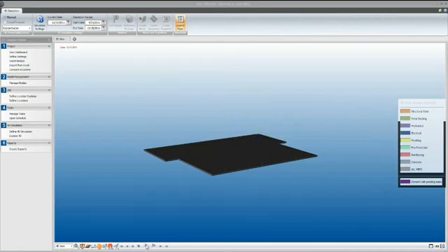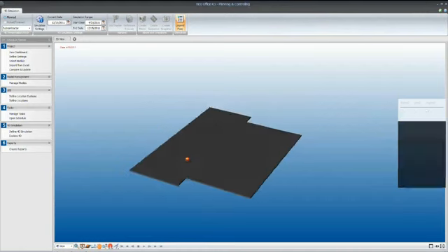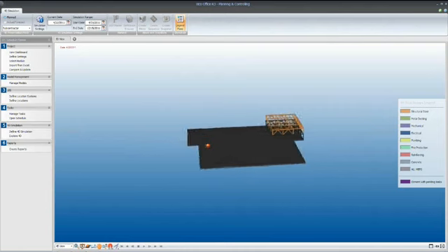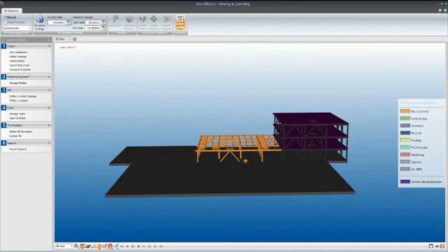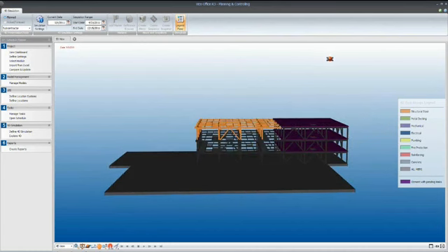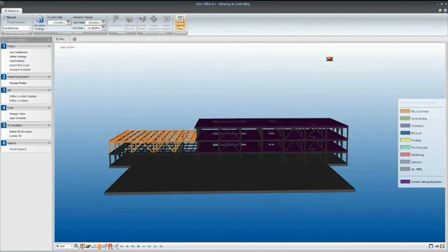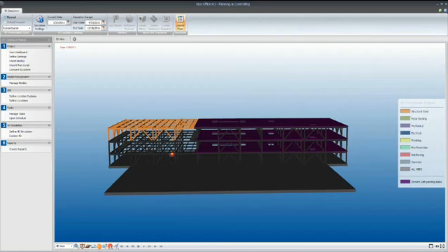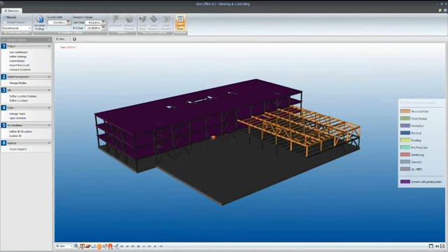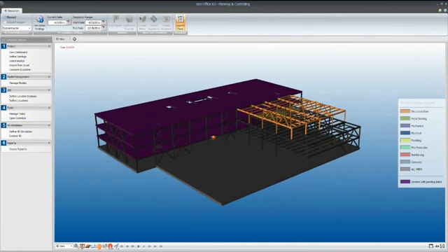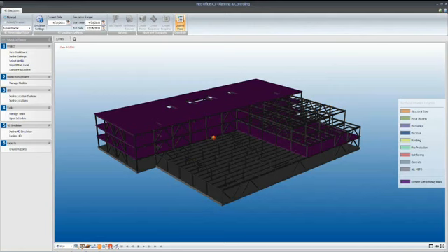Again, the 4D simulation is really a great tool for helping to communicate the construction plan to everyone on site. It should be used anytime you're planning and optimizing a schedule, and anytime you might be looking at ways or opportunities to resequence the work as a result of maybe an unknown field condition, maybe a design change from the design team has caused you to hold off work in one location.